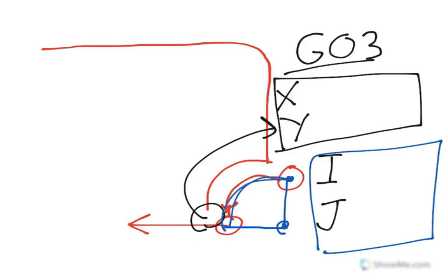Notice it's smaller than the actual arc of our piece, and above, the arc that we traversed was actually larger than our actual piece. So our final x is going to be 4.75. Remember to keep in accordance to our radius we're using for our tool. Our y is going to be a negative 5.25.